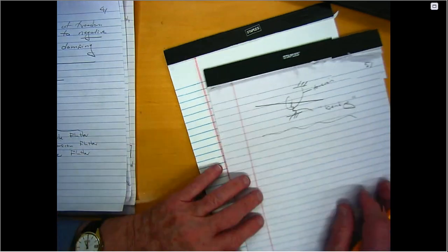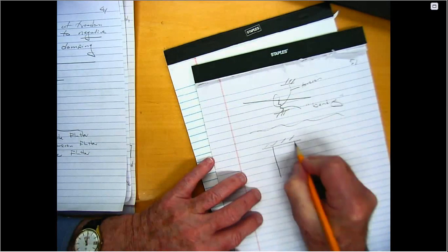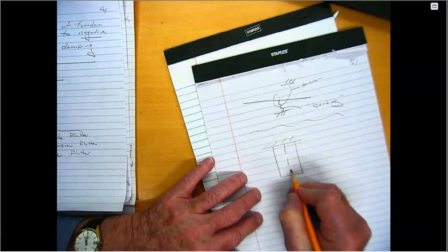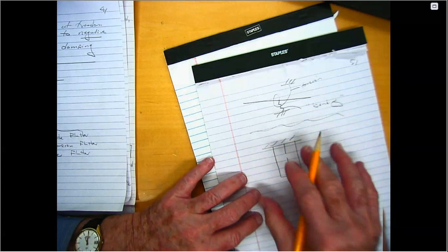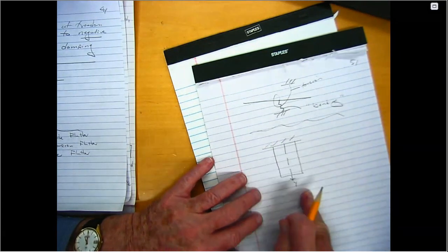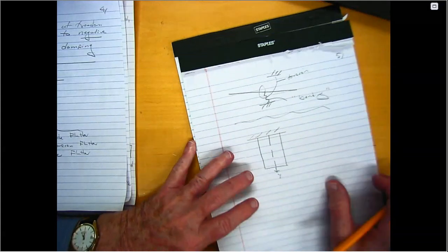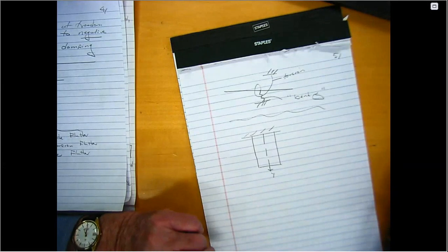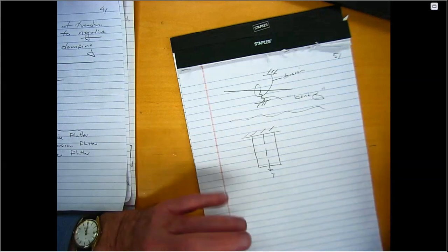Okay. So here's our wing, and here's our elastic axis for this one. And now we're going to let this wing have twisting about the elastic axis. But we're also going to allow for bending of the elastic axis. And to get coupled bending-torsion flutter, we need to allow for both. So what do we need to do? Well, we need to write down the equations of motion, which means we need to write down virtual work, potential energy, kinetic energy, and all the rest of it, right? Let's do it.